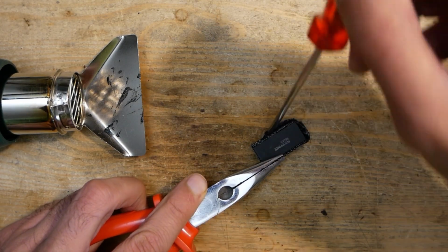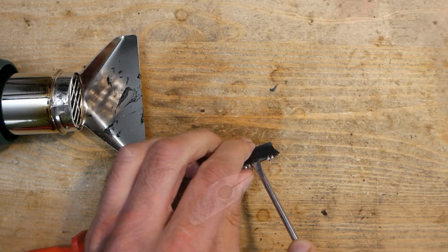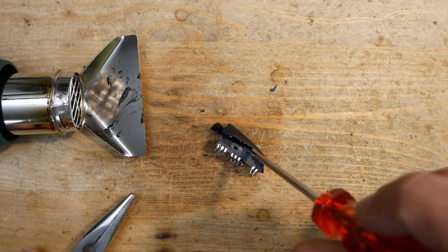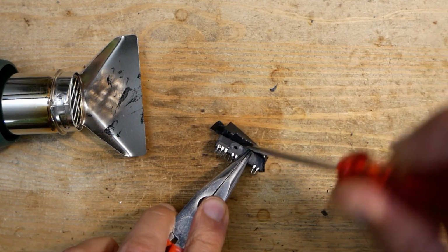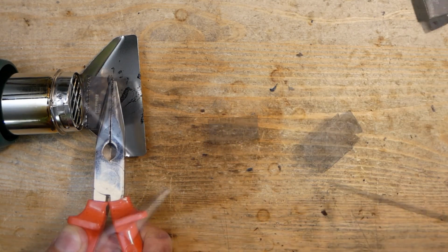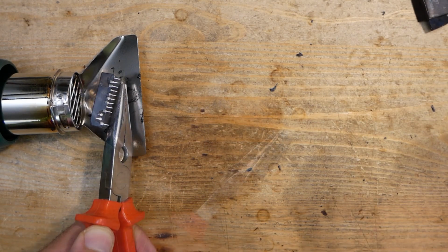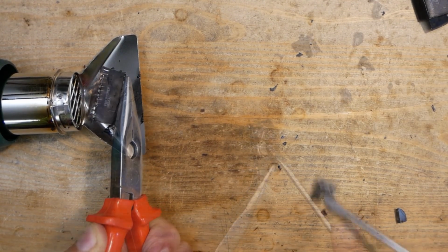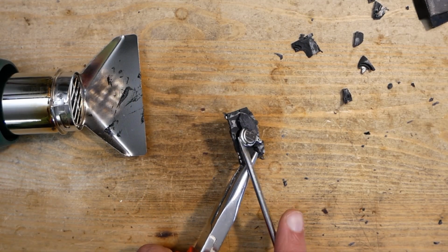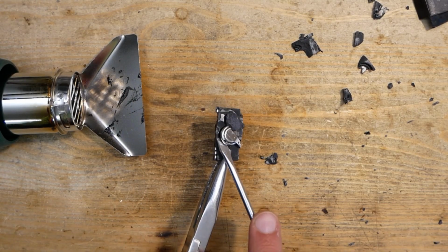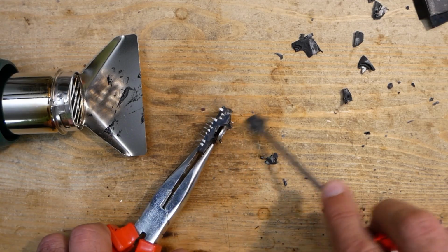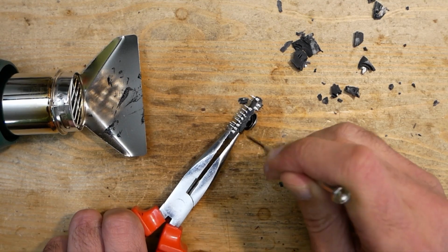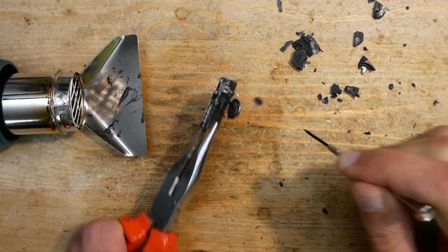First, you have to heat up the plastic cover all around until you can squeeze a flat screwdriver along the edge. Then you just have to push the plastic to the side along the whole perimeter until the plastic cover falls off. After that, you just continue to heat up the resin, and as long as it's hot, press the screwdriver into it. It is so brittle that it just falls apart, leaving all the internals absolutely clean. The only places where I needed a couple of rounds of heating and scratching with a screwdriver is between the pins of the IC.